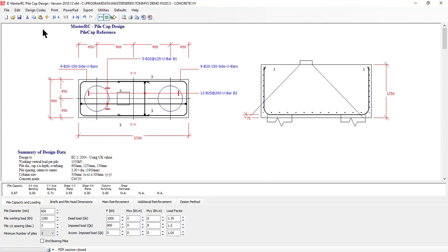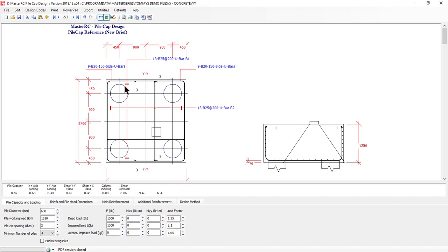If I was then to go and look at my second example, this is a 4-pile pile cap, and again the column is eccentric. I can then suddenly turn around and say, well, actually I want to create the imposed loading from wind or whatever gives me 120 kilonewton meter moment in both axes. And obviously that's not really going to worry this little very deep.